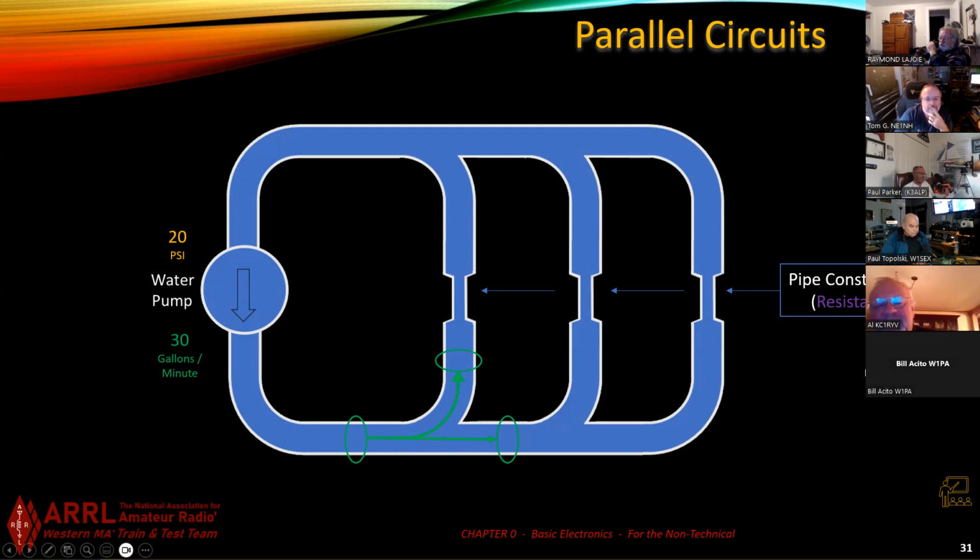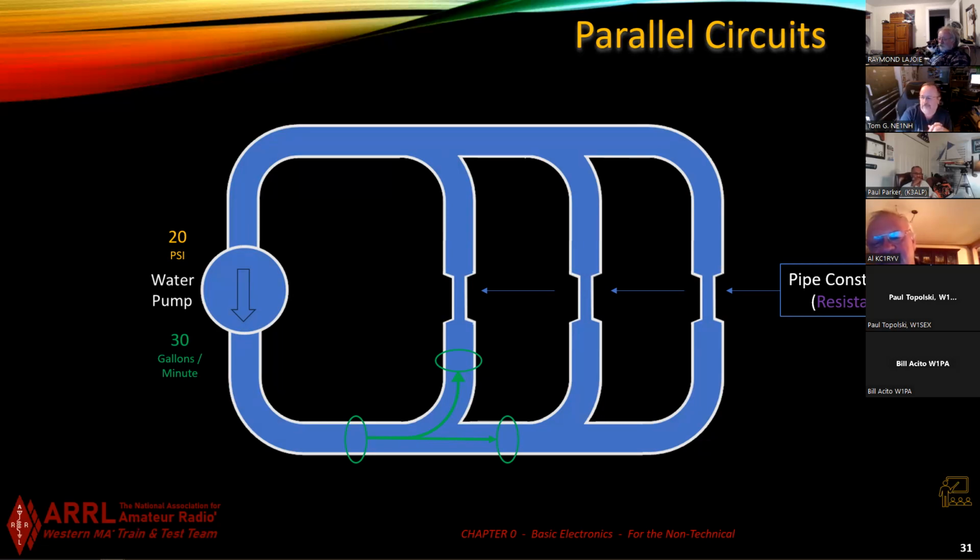Right? So I look at this, well, you want to relate it to water. We have radiant heat in the floor of our house. Right, so it's all balanced through the manifold, and as you travel further, the first restriction would have to be the greatest, because without a restriction at that first pipe, it would all just flow right past it to the last pipe. So you've got to back things up in order.